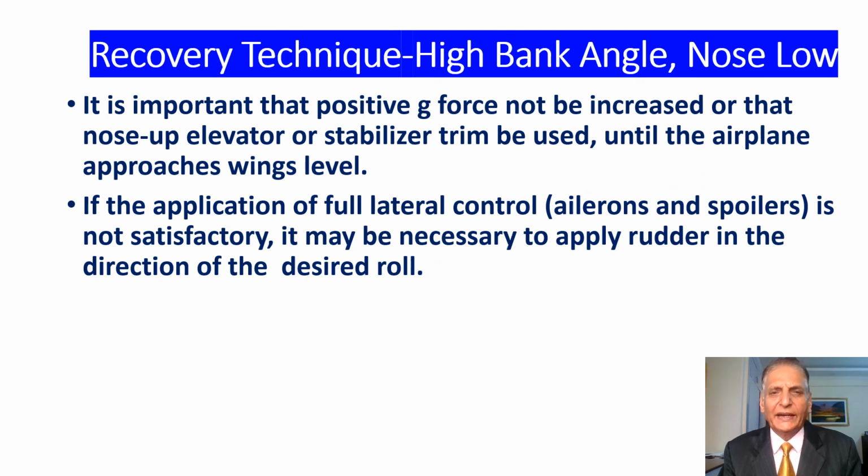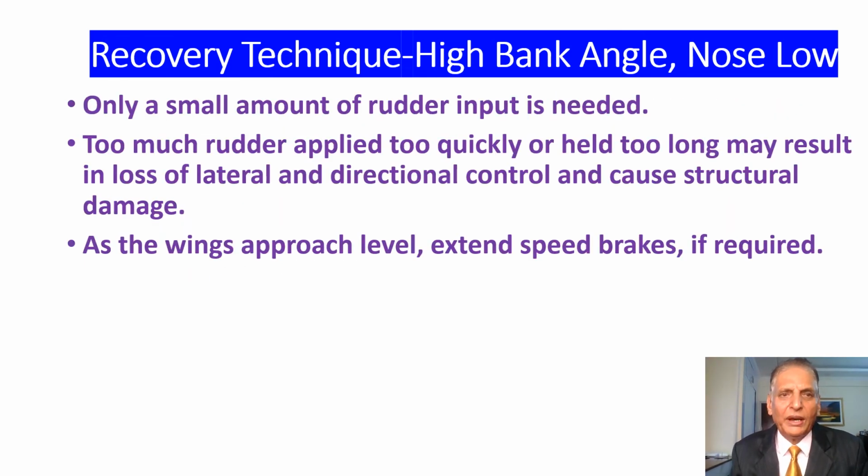It is important that positive G-force not be increased or that nose-up elevator or stabilizer trim be used until the airplane approaches wings level. If the application of full lateral control, that is ailerons and spoilers, is not satisfactory, it may be necessary to apply rudder in the direction of the desired roll. Only a small amount of rudder input is needed.